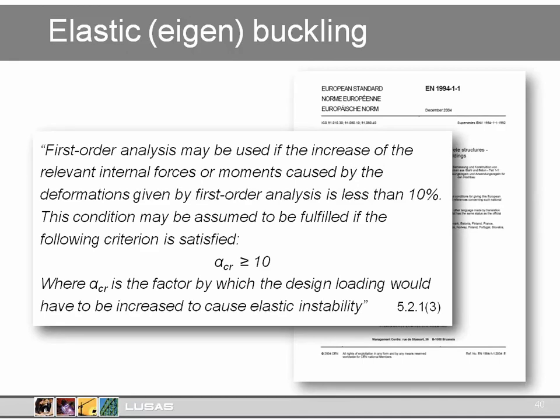On the contrary, Eurocode does. This clause tells us that second order analysis is required where the effects of large deformation are greater than 10% on top of a first order analysis. To confirm that literally, you need to do the second order analysis anyway.